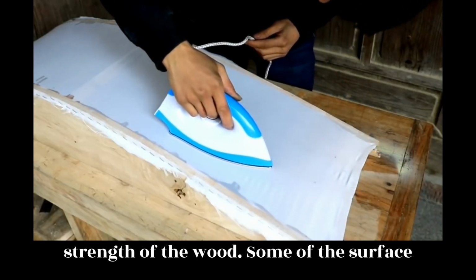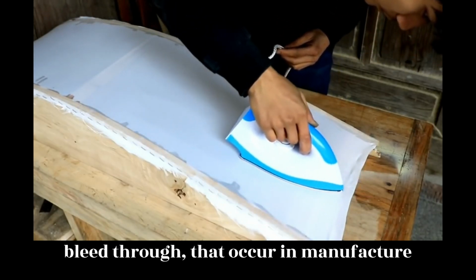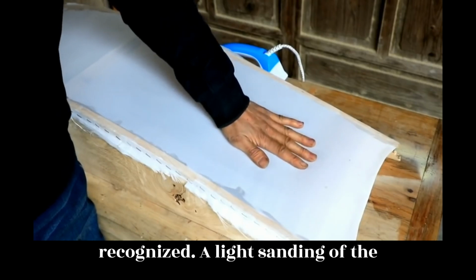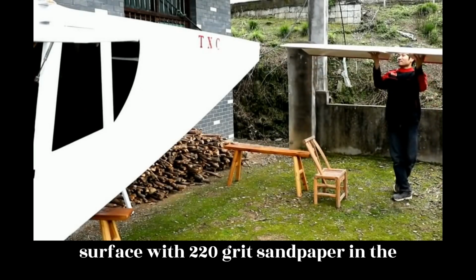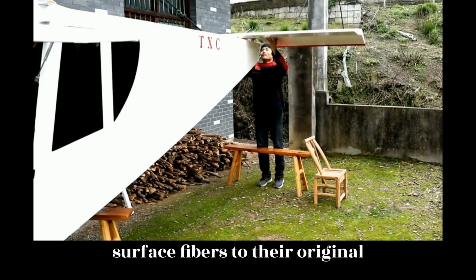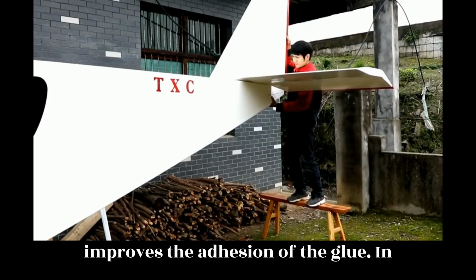Glue joints made on surfaces that are covered with crushed fibers do not develop the normal full strength of the wood. Some of the surface changes in plywood, such as glazing and bleed-through, that occur in manufacture and may interfere with the adhesion of glue and secondary gluing are easily recognized. A light sanding of the surface with 220 grit sandpaper in the direction of the grain restores the surface fibers to their original condition, removes the gloss, and improves the adhesion of the glue.